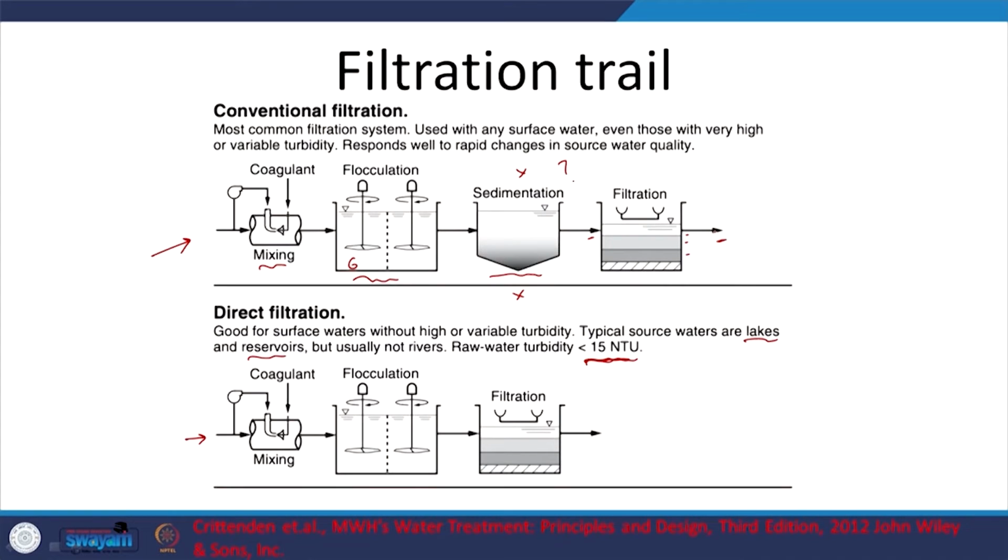So, that is one reason why you will usually have sedimentation prior to filtration, especially if the turbidity is relatively high.